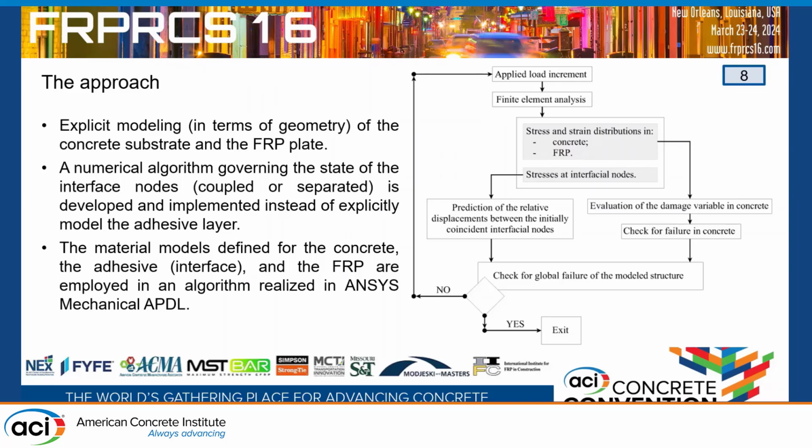So the approach: all the components of the experimental setup, which will appear in the next slide, are explicitly modeled in terms of geometry, except for the adhesive layer, in a 3D setup. Then a numerical algorithm governing the state of the interface nodes, which are initially fully coupled and then uncoupled as a function of the developed shear stress at the interface, is applied in a general purpose code for finite element analysis, ANSYS Mechanical APDL.